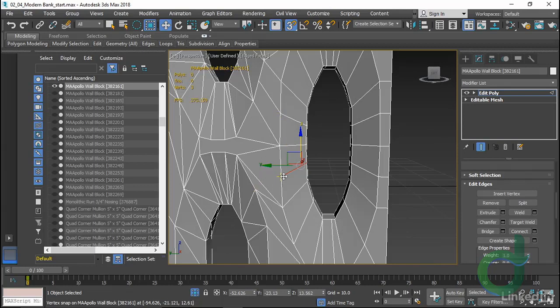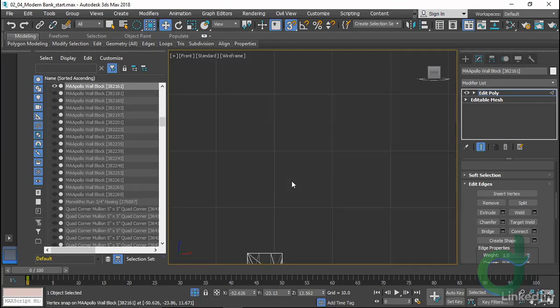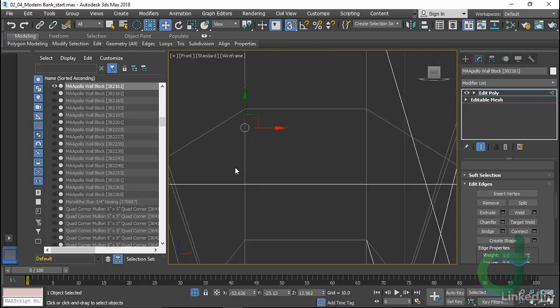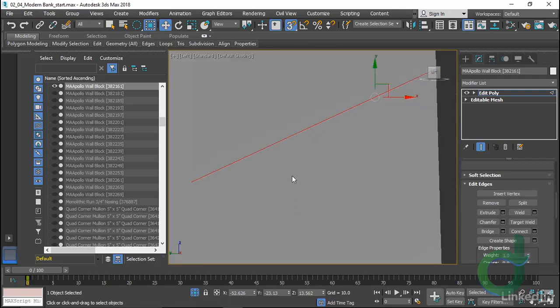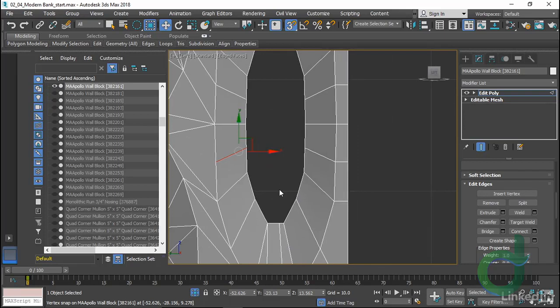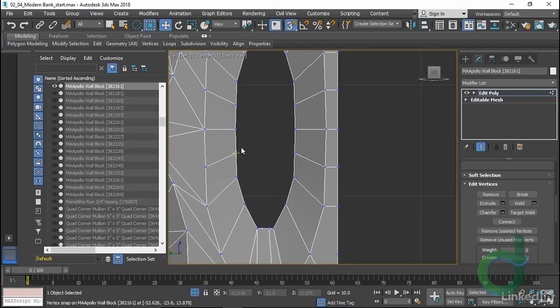where this edge comes to an edge instead of being contiguous, so that I can sort that out as needed. What I'm after there, though, is that in a front view, or actually a left view it looks like, I can now scale out vertices symmetrically to add a little more curve to this mesh. I'll start out by looking at the inside ones, changing my selection marquee back to a rectangle and picking pairs here on either side of the center, some manual symmetry.